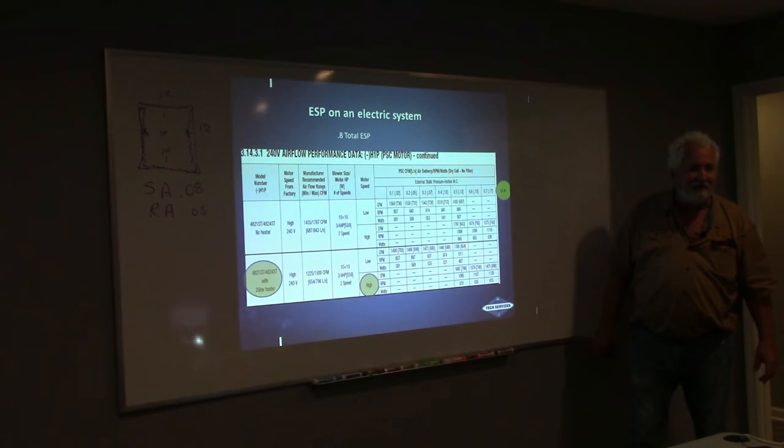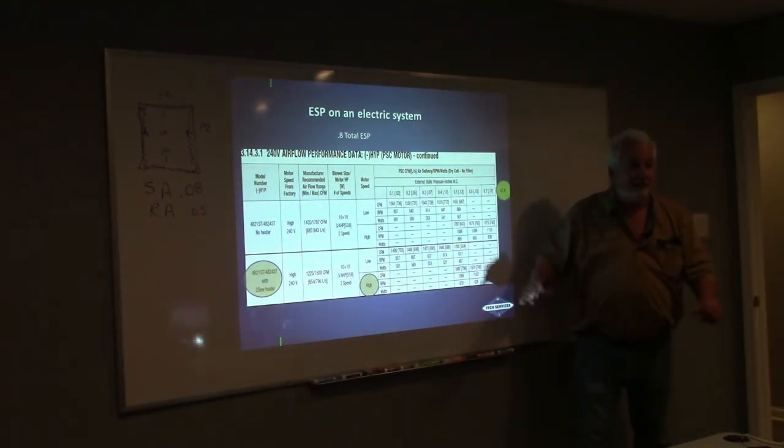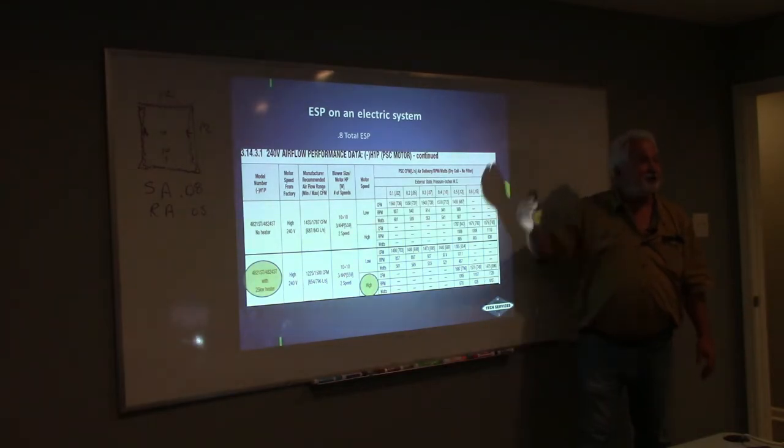What's going on now, guys? Is that blower going to work? For a while. So what is going to happen? Okay, so look, let's see, I'm going to run the scenario. The blower's going to run. Is it going to get hot? Is the motor going to heat up with all this resistance? Okay, the blower heats up and it gets really hot and it shuts down once that limit kicks, right?